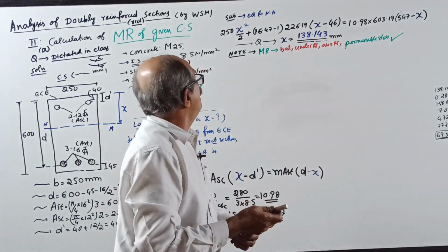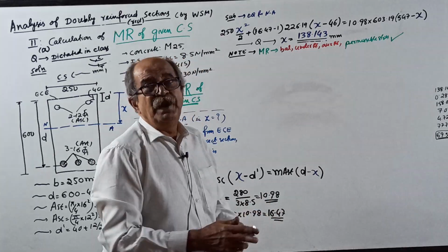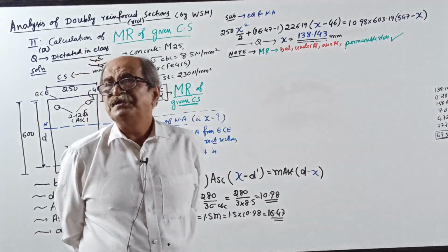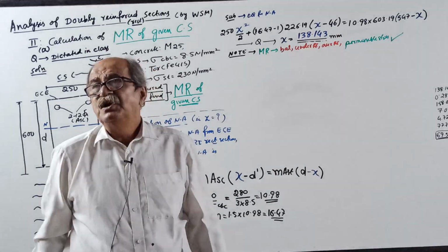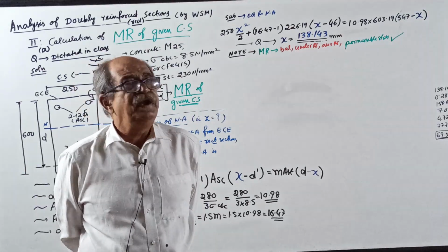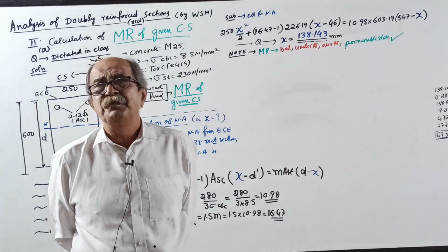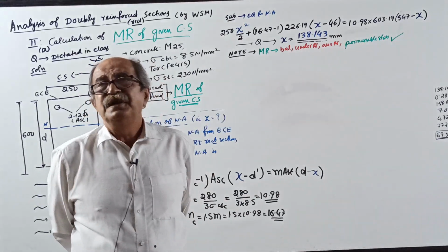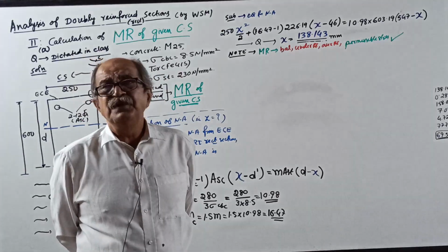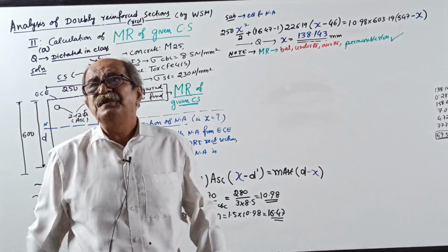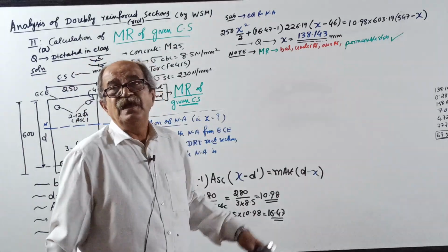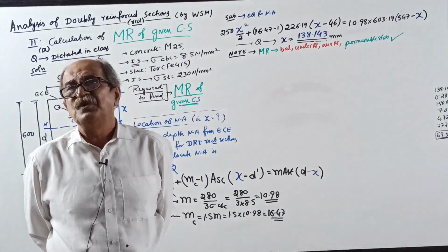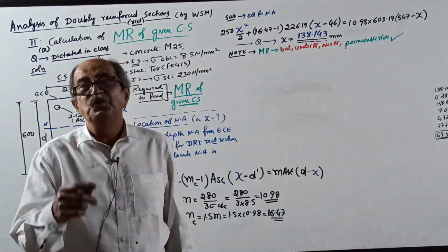Okay, start now. First, I'll do one thing. Now make a note. For a singly reinforced section, we can write the equation or expression for MR either in terms of compression or in terms of tension. Just replace M by MR, right hand side, permissible stress, that's all. For a doubly reinforced section, the expression for M in terms of compression is simplified. You know it already. But do not say it is not possible to write in terms of tension. It is possible, but you know the struggling.